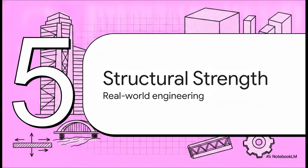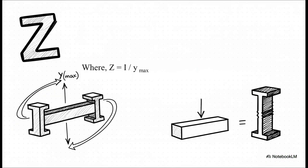All right, final stop. Section 5, calculating structural strength. Enter the section modulus, represented by the big letter Z. This is the elegant solution engineers use to measure a cross-section's physical resistance to bending. Z is calculated by taking the beam's moment of inertia I, which is basically how its shape is distributed, and dividing it by Y max, which, as we just learned, is the maximum distance from the neutral axis to the extreme outermost fiber. A higher section modulus means a stronger, stiffer beam.